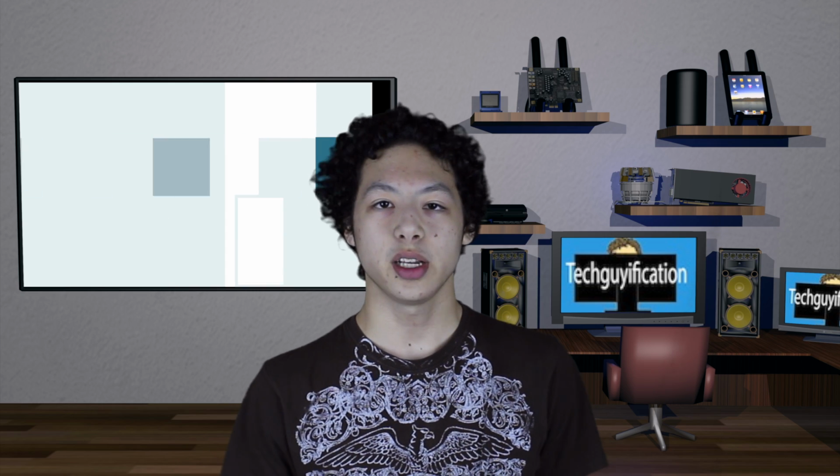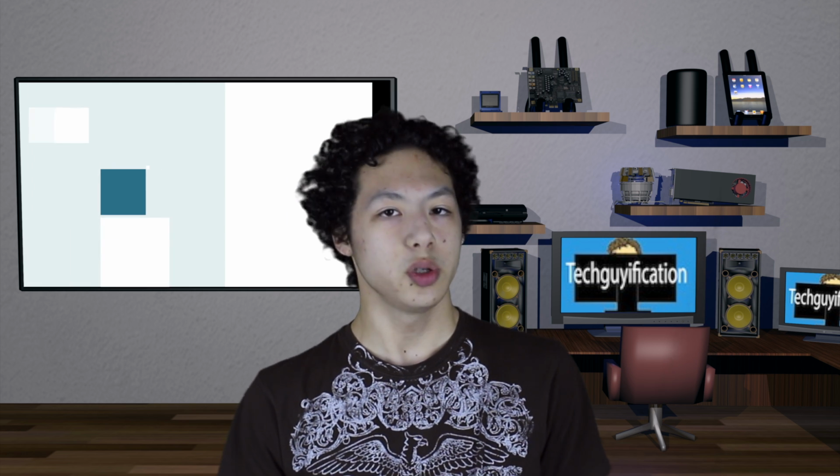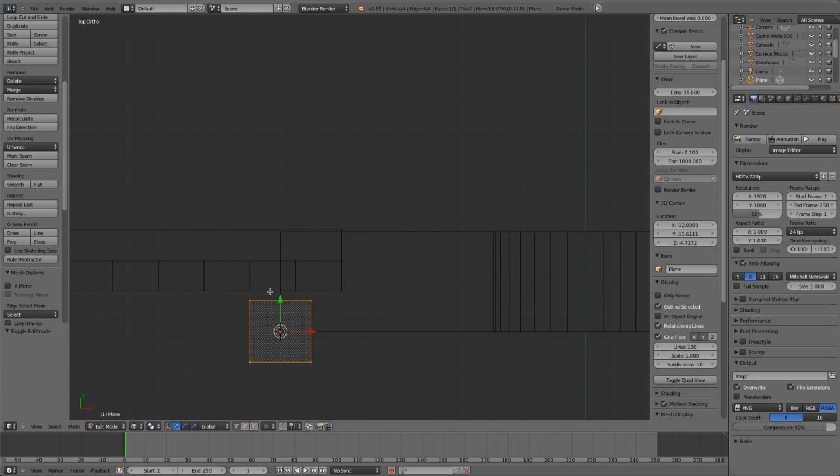Now select this plane object which we just created, tab into edit mode, and then select the top two vertices by right-clicking on one, then holding down Shift and right-clicking on the other, and move them down using the green arrow as shown. With these same two vertices selected, press E to extrude, then Y to lock it to the Y axis, and then move them up as shown.